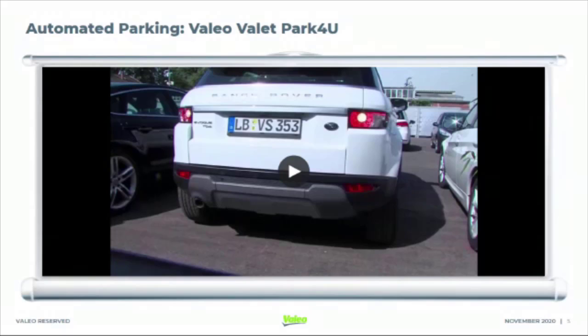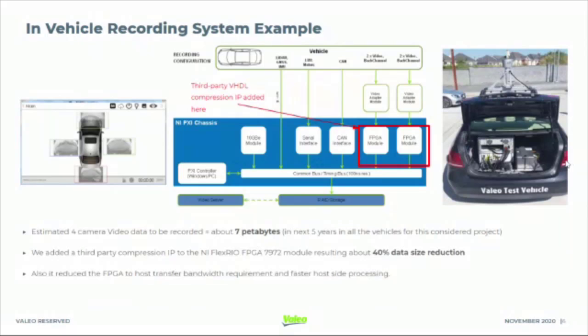So the recording system, this is one typical at our Valeo. What we have, this is a test car on the right side, and we put the PXI system, NI FlexRIO there, which captures from the vehicle the streams of these 4 cameras. You can see here each FPGA card handles 2 cameras, and then there are other sensors like CAN, LiDARs.